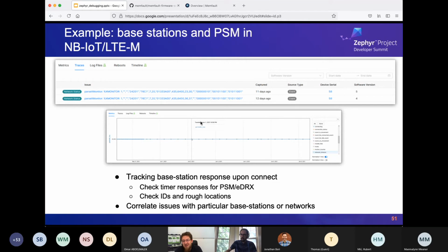But in certain cases, you see when this value starts changing, it will mess with your low power operation or devices will start behaving differently. And using the alerts function, where you pretty much monitor the metric for a change, it's very easy to automatically see and then go and correct either the settings or the firmware revision.